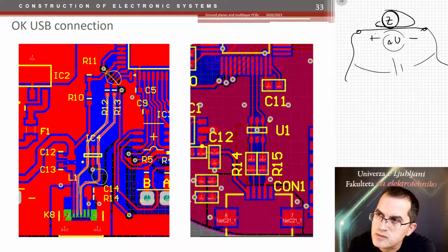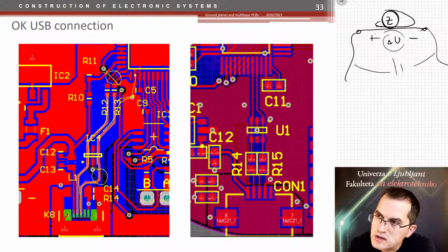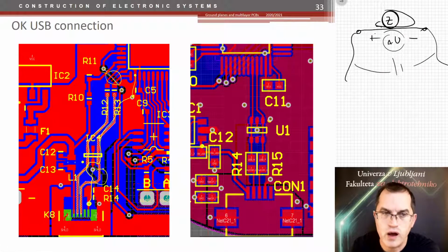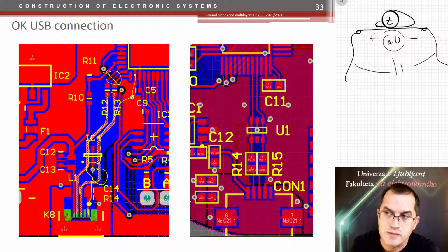to this pin, which is a ground pin, returns back to this wire, changes on the bottom layer, then it can actually follow the currents of these two layers. Here it will go a little bit around and then follow back to this pin where we have the wire to connect the top layer again to this connector. So there are small interrupts in the ground plane, but not that severe.